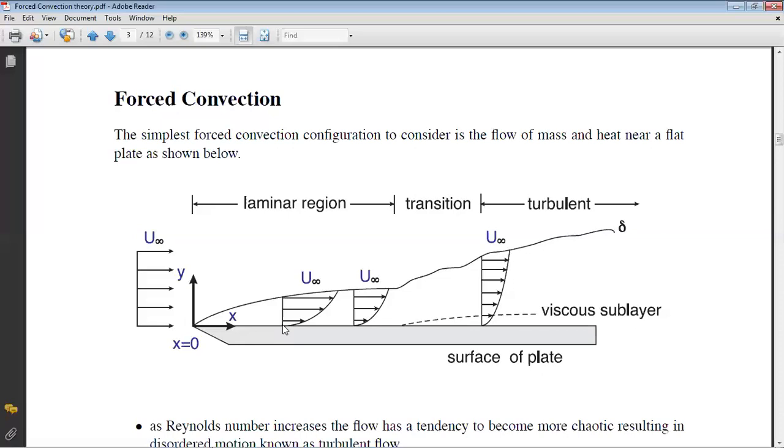Now this point is at rest because of the contact with the stationary surface. So this induces a resistance to the next upper layer of the fluid. As a result, the velocity will come down. This will in turn reduce the velocity of the second upper layer.